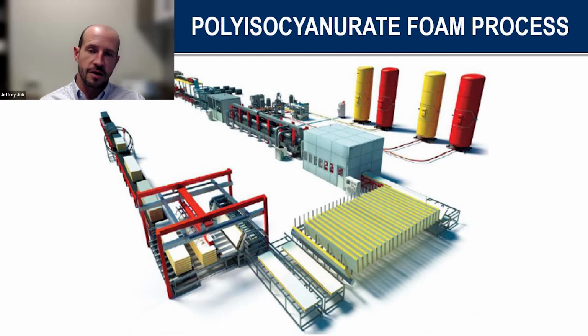Coated glass is a glass mat typically coated in a mineral substance, inorganic, so no cellulose, no paper, not going to absorb any water, and will not be a source for mold growth. So that tends to be the higher quality facer being used in the roofing industry.